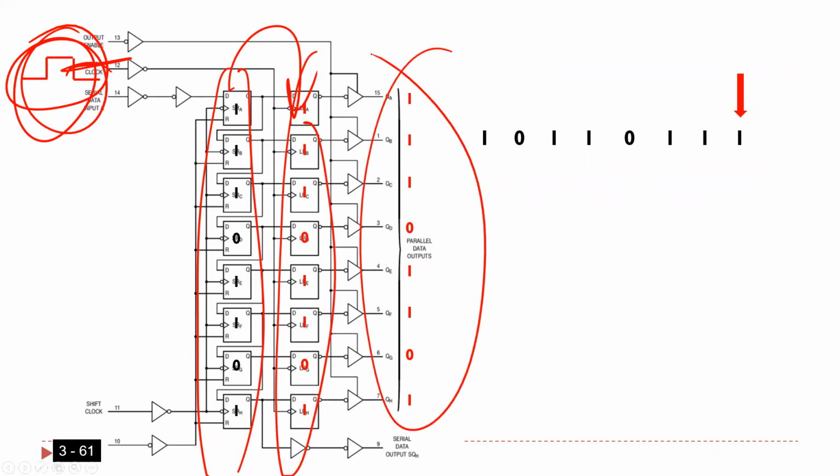Is that okay, guys? Number 1, you should understand from what I said, you will not always need a shift register. We use it in order to save pins, so that the microcontroller can be connected to many devices. How did we save it? Because for sure there are good things and bad things. Nothing is for free. The good thing is, instead of using 6 pins, I'm going to use only 3 pins from the microcontroller. That's a good thing, right?